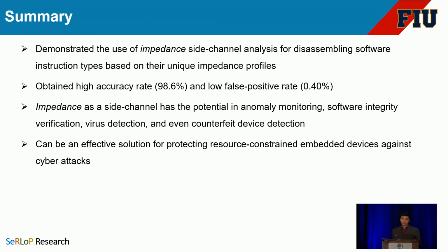So in summary, we demonstrated the use of impedance side channel analysis for disassembling software instruction types, and we observed a low false positive rate and high accuracy rate. And in a paper, we also describe how impedance has the potential in anomaly monitoring, software integrity verification, virus detection, and even detecting counterfeit components.